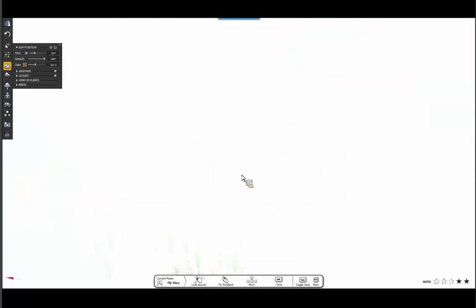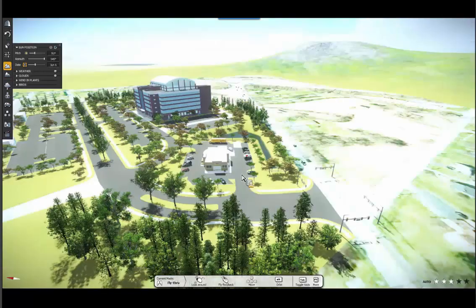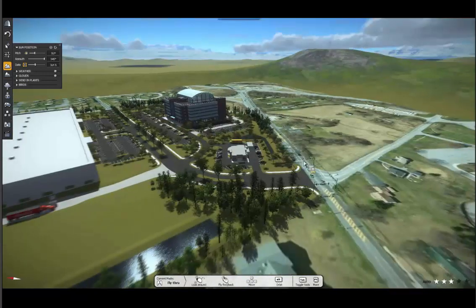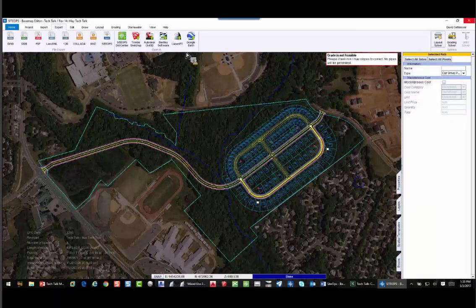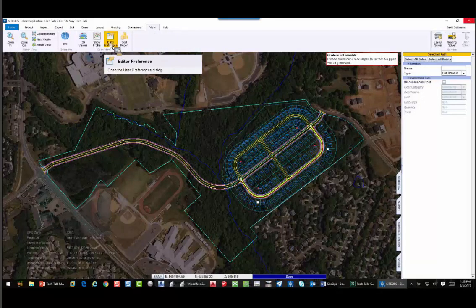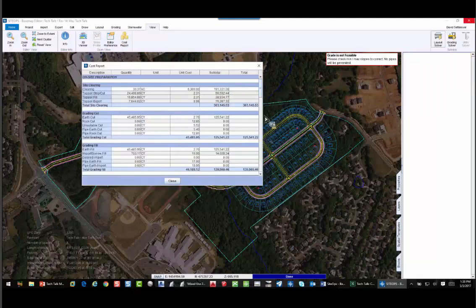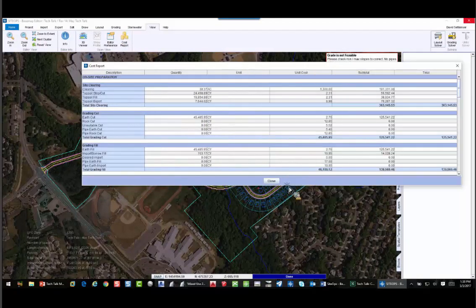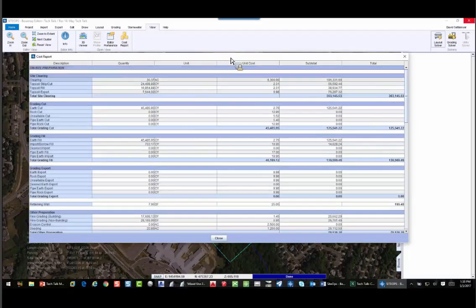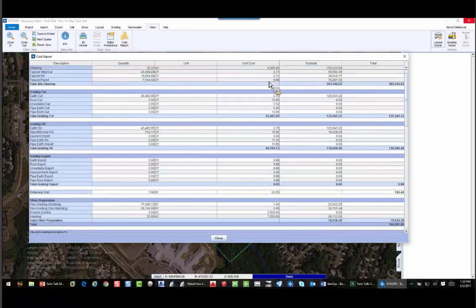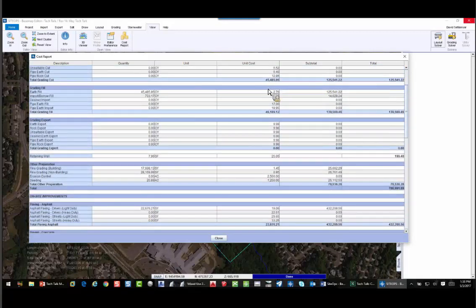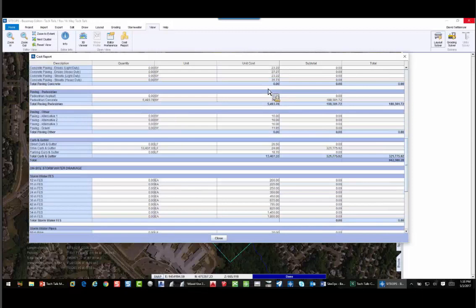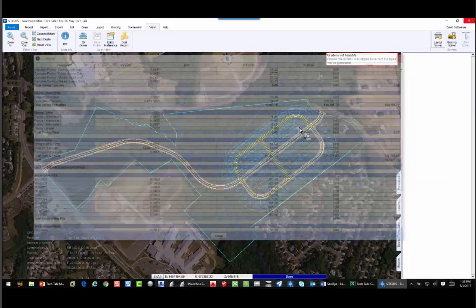And this is the talk about not just doing a 500 lot subdivision in an hour. It's doing the design. It's getting a budget, because one thing SiteOps delivers is on the back end, you keep playing with it. You can do some stormwater. You can add your own costs. I can offset the center line and say it costs so much per linear foot of roadway for the water line. I'm going to draw sewer in there manually. Say it's a sewer main or a sewer line, and every point where I make a turn, that's a manhole. And you can come in and get into your clearing, your topsoil, retaining walls, asphalt, curb, gutter, and all this kind of stuff to get to a detailed budget. So they're not just looking at a guess. They're looking at something substantial. They can say, yep, that looks pretty good.